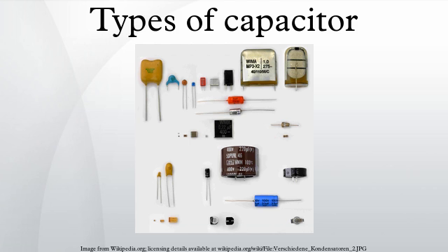The time curve of self-discharge over insulation resistance with decreasing capacitor voltage follows the formula, with stored DC voltage V0 and self-discharge constant tau. Thus, after time tau the voltage drops to 37% of the initial value. The self-discharge constant is an important parameter for the insulation of the dielectric between the electrodes of ceramic and film capacitors. For example, a capacitor can be used as the time-determining component for time relays or for storing a voltage value as in sample and hold circuits or operational amplifiers.